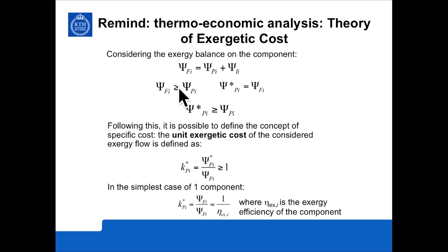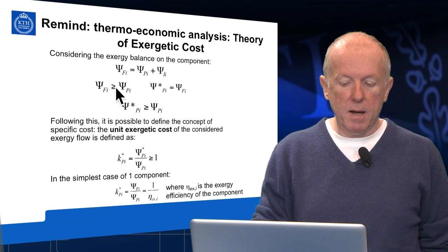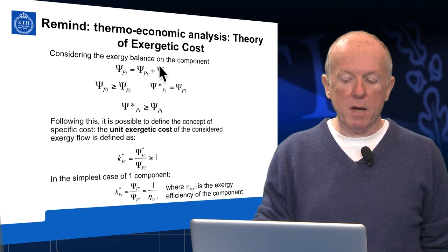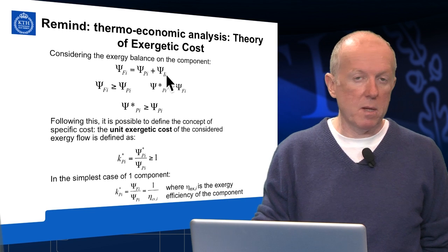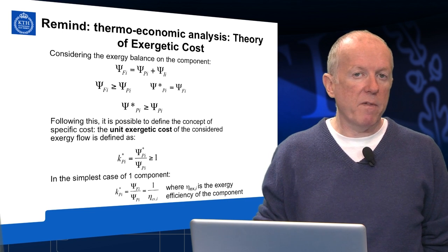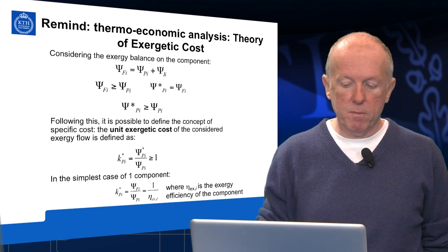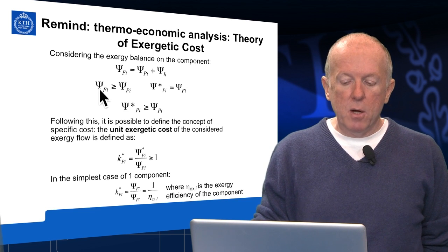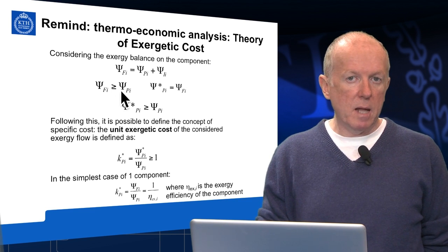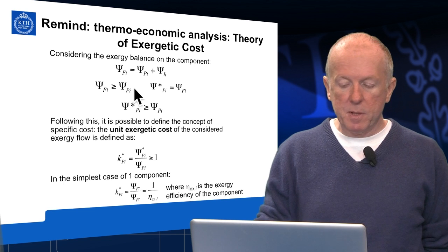The equality only holds in the case in which the irreversibility is equal to 0, which is, of course, the case of a reversible operation, an ideal case. So in general, ψ_F is higher than ψ_P.